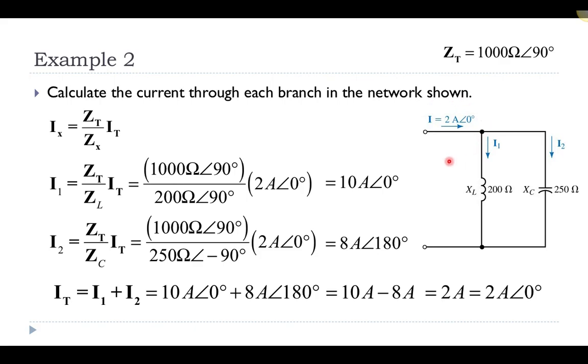So similar to the previous examples that we saw, it's possible that you can have current entering a junction, and the current through an individual component, the maximum current, can actually be larger than the current that's entering, because it's in parallel with another component that's out of phase with it, and when one of them is a maximum, the other one is exactly a minimum, a negative, and when you add those two values together, they do give you what the source is.